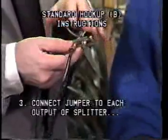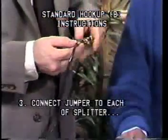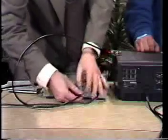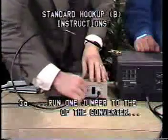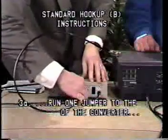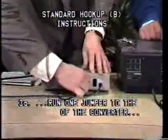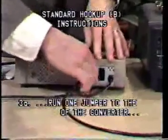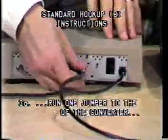The signal is now split in two. One side is going, now this side is going where? To the input of the cable converter. Okay, the input of the cable converter. It says input on the back, and I'll just screw this in.